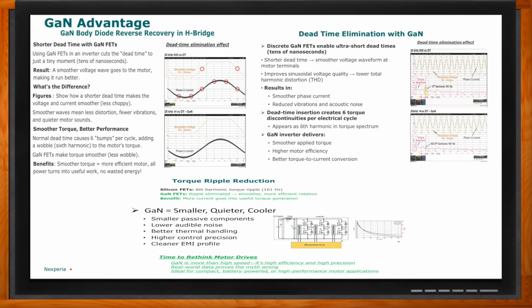You can see it in the pictures that there's a shorter dead time that will make voltage and the current smoother, less choppy, so much smoother operation. That means lower distortion, fewer vibrations, and a quieter motor.